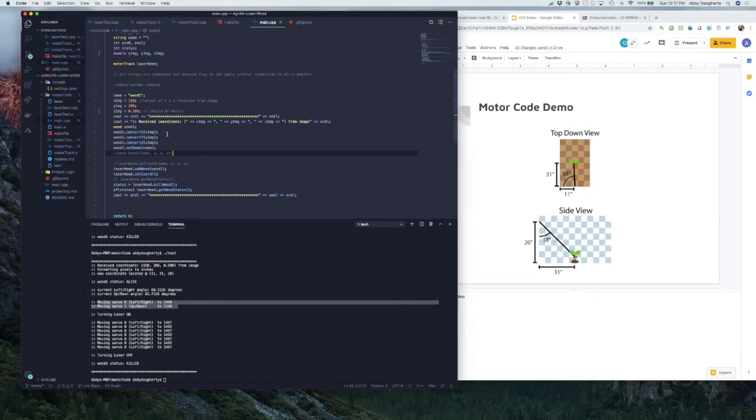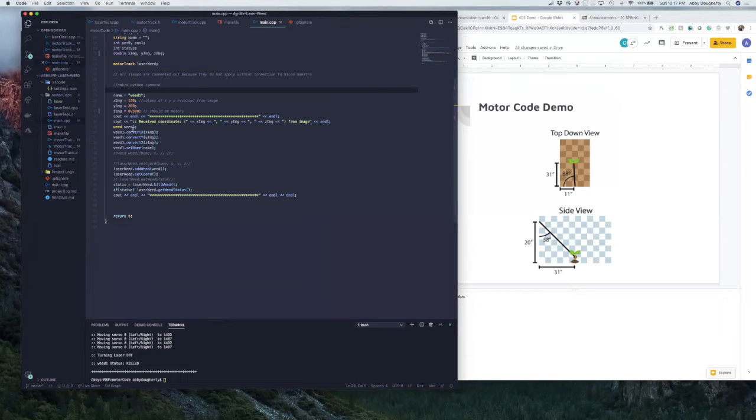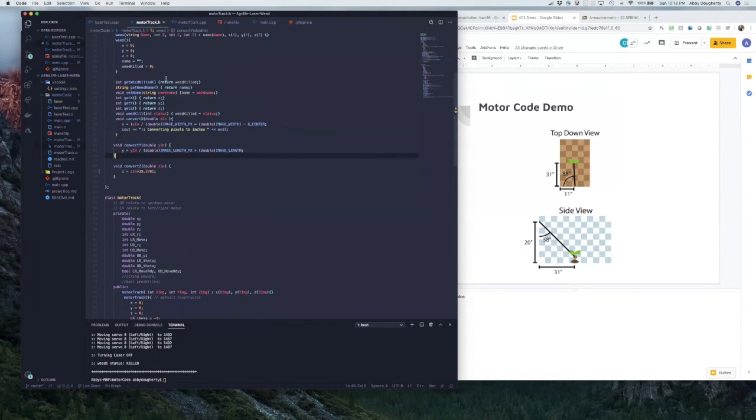If you look at the code, the first thing it does is we're gonna see this X image, and we're gonna get pixel values, X and Y from the camera, and we're gonna get a Z value in millimeters, how far away the weed is from the top of the frame. And then those will be converted with simple multiplication into inches. We chose to do it this way because we figured it'd be way easier to verify. If we have physical inches locations under it, it'll be easier to measure and see if we're going to the right place.